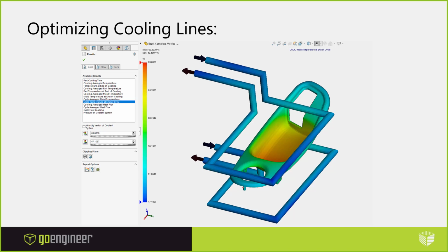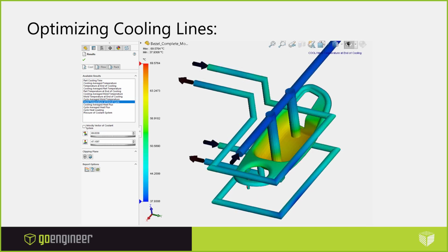You can change your sketch paths in the cooling lines. You can have 3D modeled cooling lines, or you can just have sketch lines, and then when you go through the domain assignment, you can tell it that these are cooling channels. So you're able to just go in and pick the sketch lines that are your cooling channels. You can use 3D sketches or 2D sketches and select these, and set the sizes of them. You can set if they're bubblers or baffles. I've got these set up as baffles, and it allows you to analyze your cooling line.